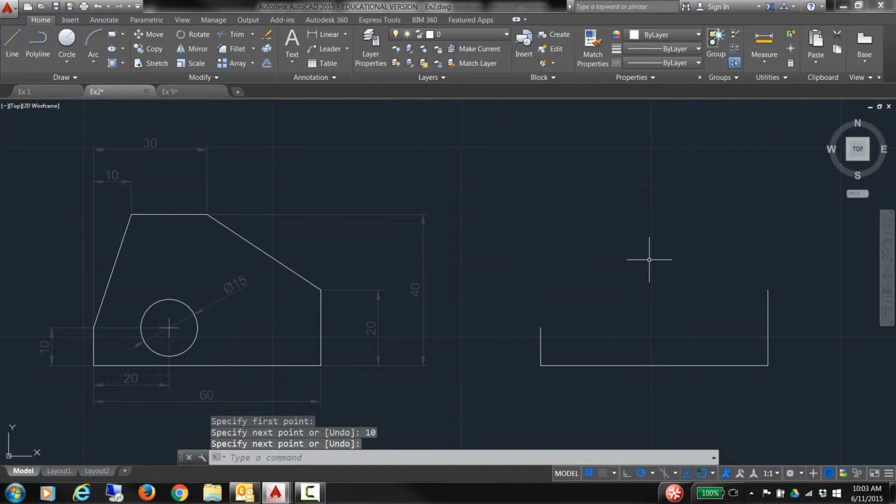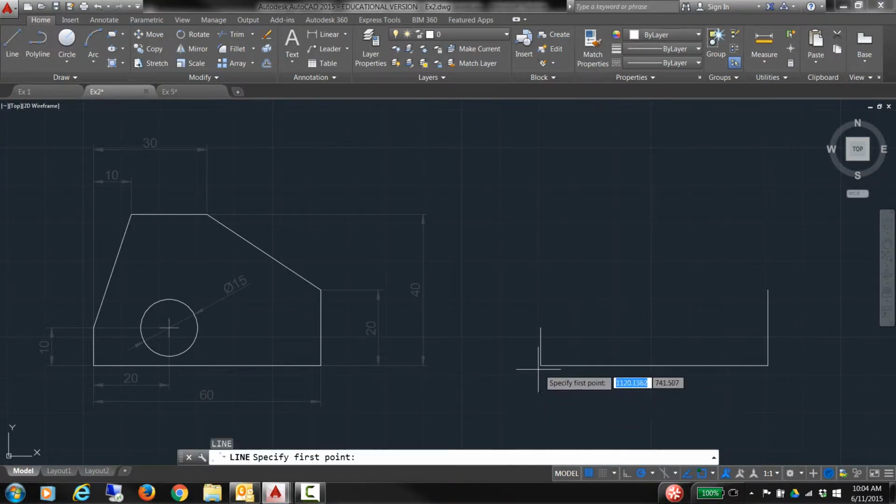Okay, so there are a couple of different ways that you could create this angle here. We're going to use a pretty straightforward concept, which involves drawing a construction line that's 30mm away from that end, and straight up past this point here, so up there somewhere, and that will give us the first part of the equation, as it were.